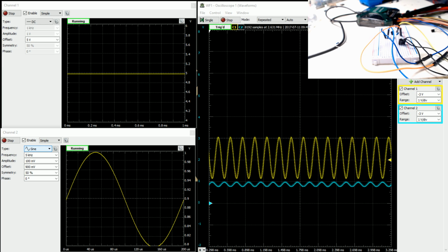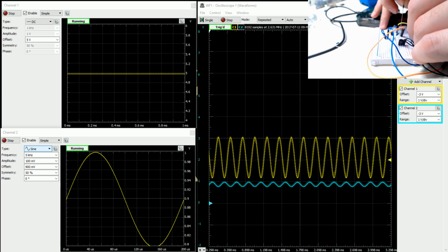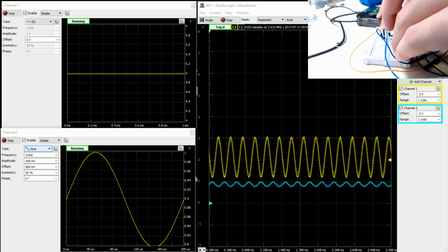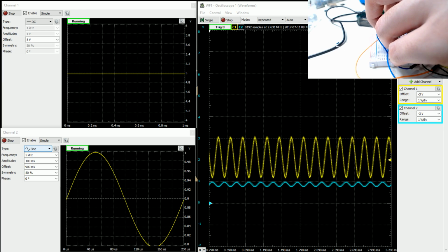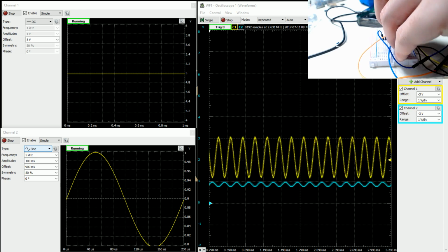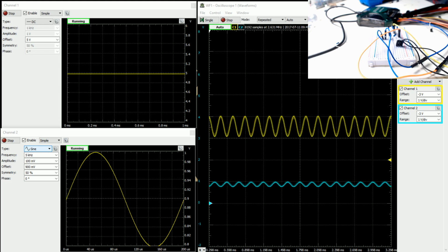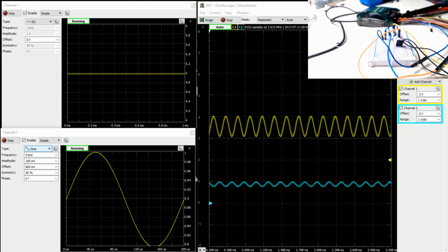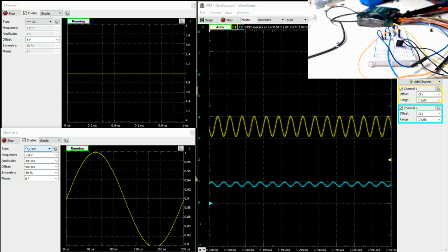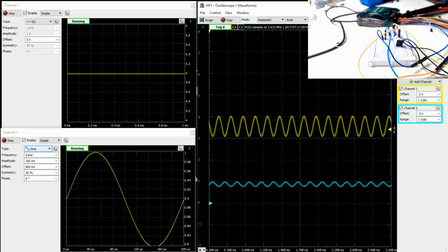What we can also do here, since we've already got it in line, is take a 10K resistor and put it in line with this other 10K resistor. That should drop the resistance by half. 2 10Ks in parallel is 5K. So now we should see that amplification drop, and there we do. So now we kind of reset the drawing board, because now our 5-to-1 ratio, so 5K to 1K, all that math changes now.